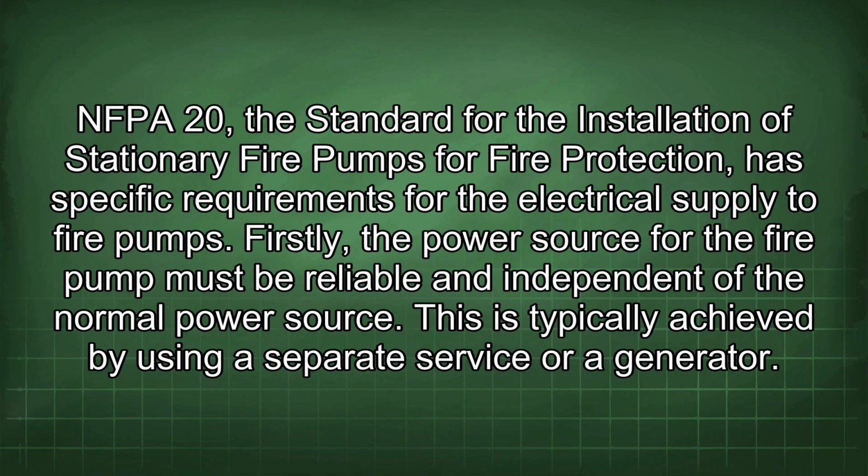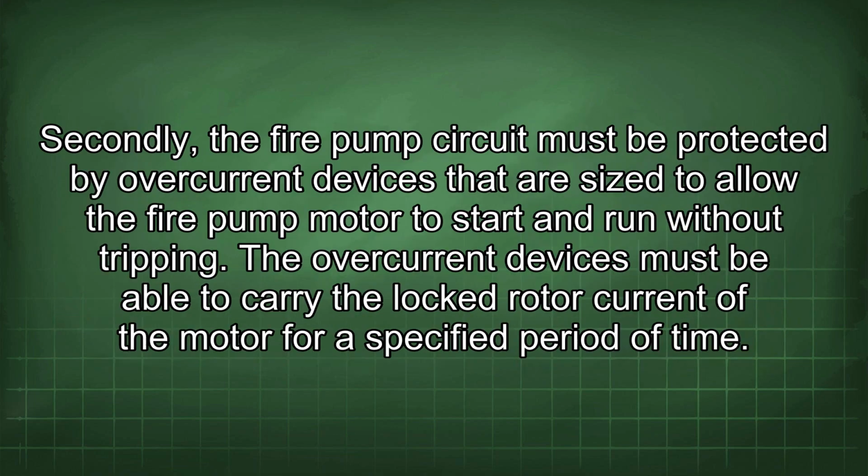NFPA 20, the standard for the installation of stationary fire pumps for fire protection, has specific requirements for the electrical supply to fire pumps. Firstly, the power source for the fire pump must be reliable and independent of the normal power source. This is typically achieved by using a separate service or a generator. Secondly, the fire pump circuit must be protected by overcurrent devices that are sized to allow the fire pump motor to start and run without tripping.